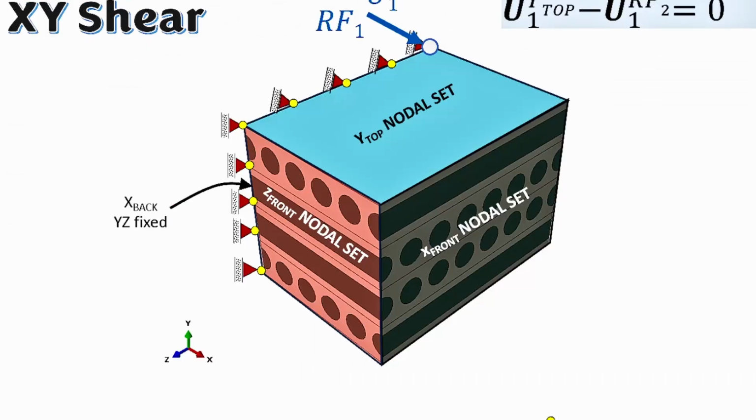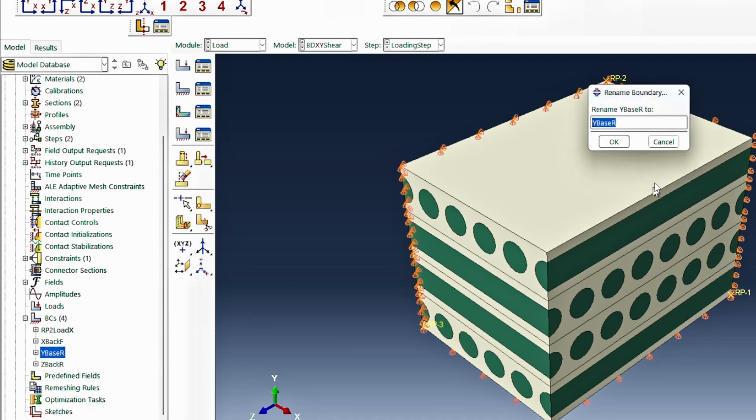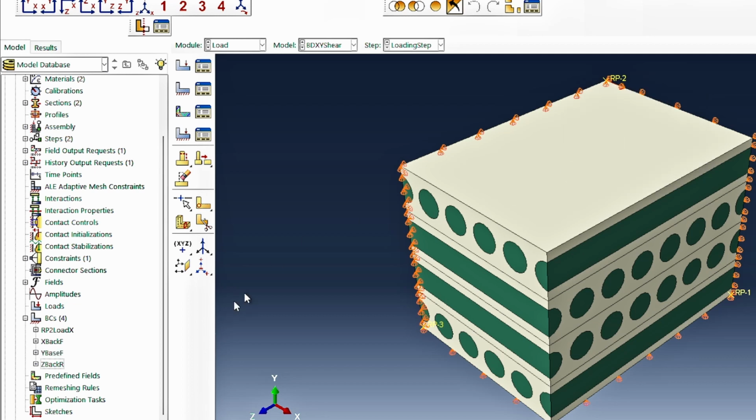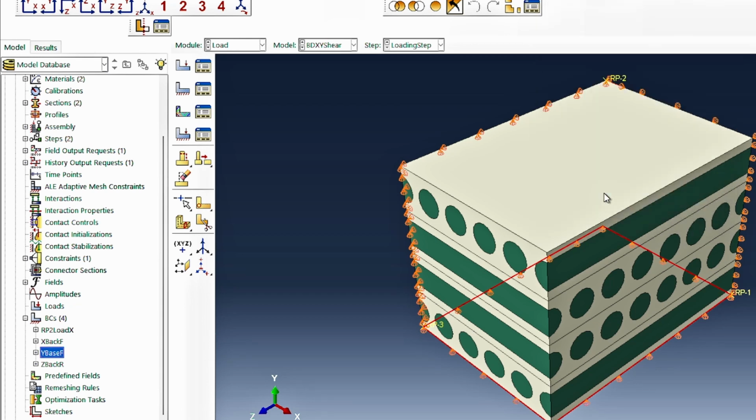So basically that node is connected to the top face and we're happy with that. The next thing we look for is that the Y base is fixed in the XZ plane. So Y base here, and it's fixed in the XZ plane. We'll change this to an F to show fixed. And if we look at that, it's in the XZ plane, so we choose those two as how it is fixed.